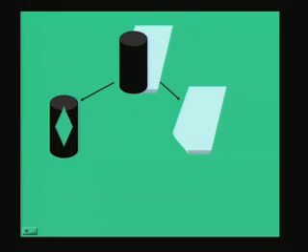So, I will say this object is a union of these 2 parts. So, I will take a cylinder which I have shaded with black for the sake of visualization, otherwise the colors have no significance, and I would like to say that the structure at the root node in constructive solid geometry in this particular example is a union of 2 different structures, a cylinder and a wedge type of structure, a rectangular parallelepiped, a very thin one where the left bottom part is truncated or broken, as you can see. So, we would like to position the cylinder at one point and take the union of these 2 structures.